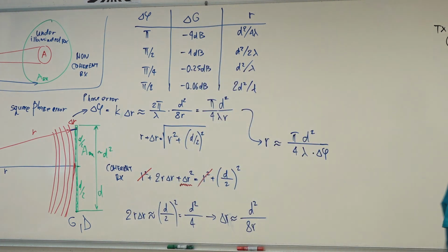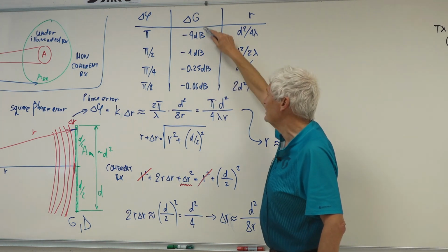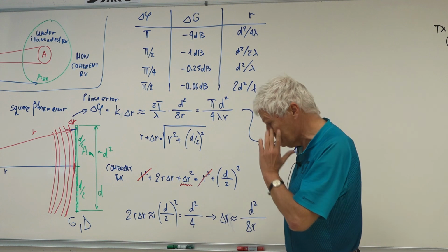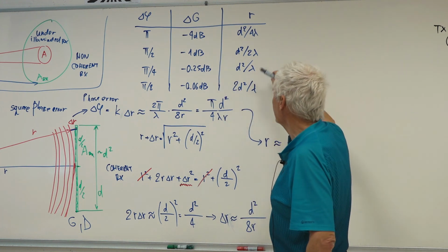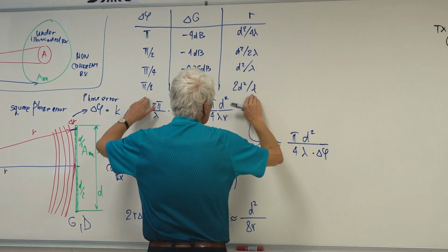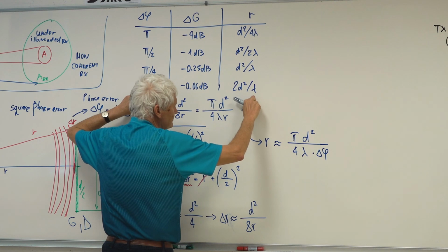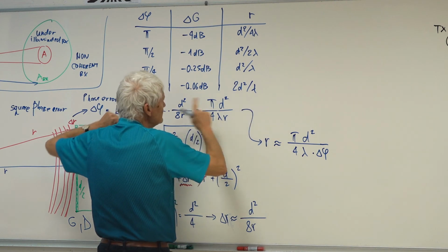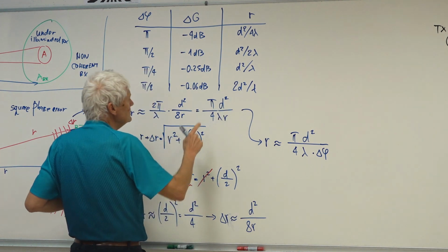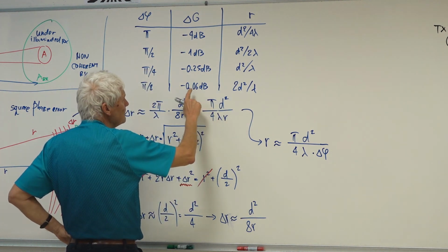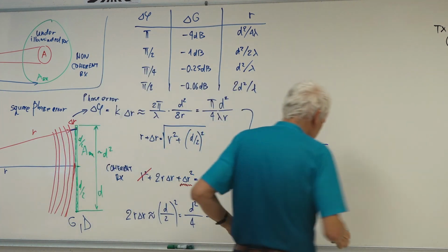At what distance does this happen? If the distance is larger than this, then the gain error is smaller than this figure here. So if I take the last figure, 2d squared over lambda, this figure is 0.06 dB, so it's a very small error.